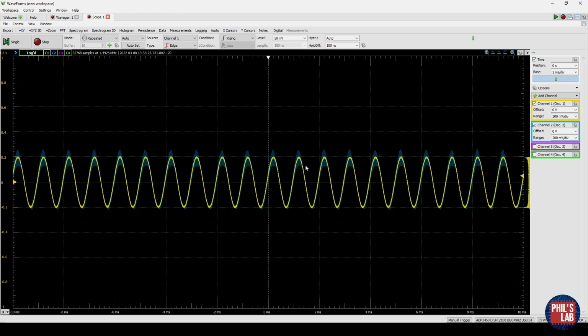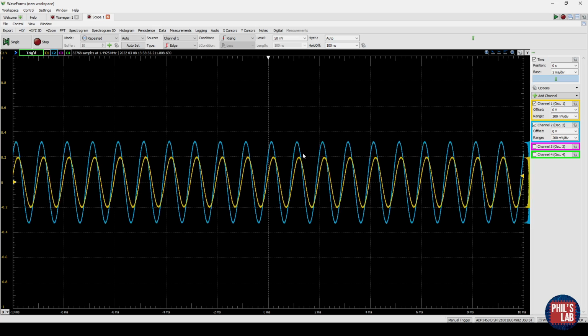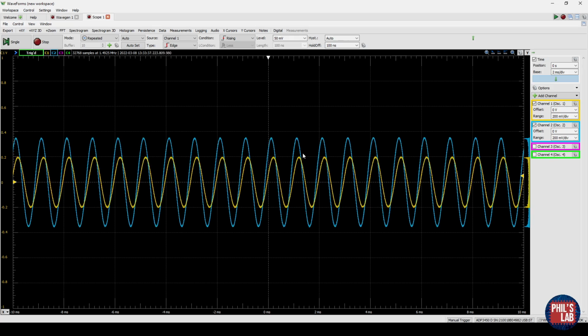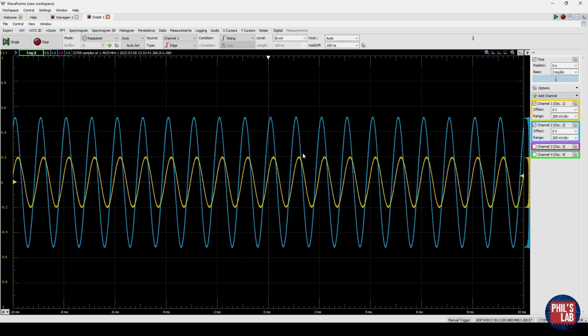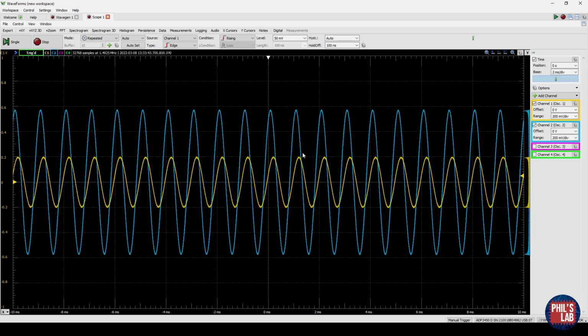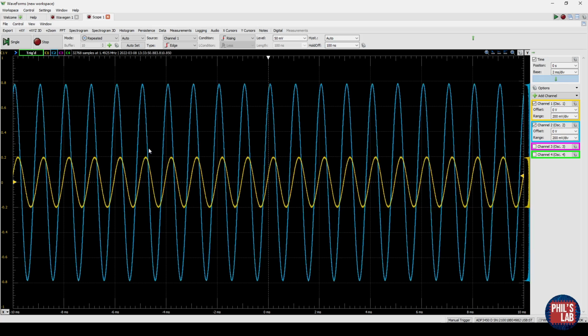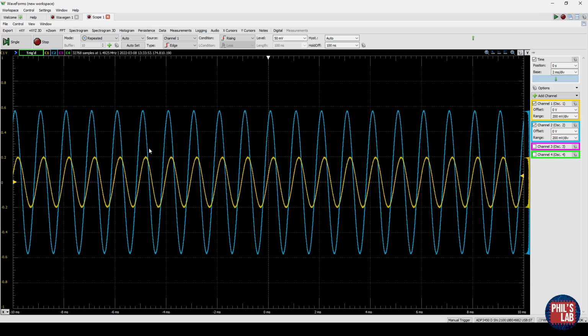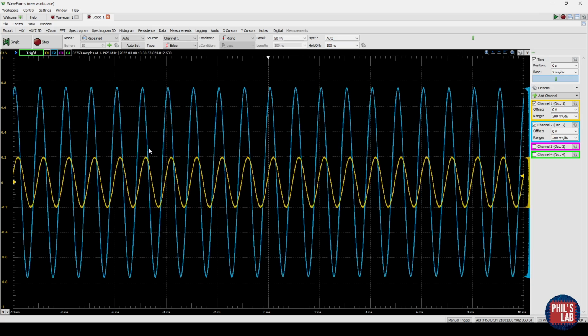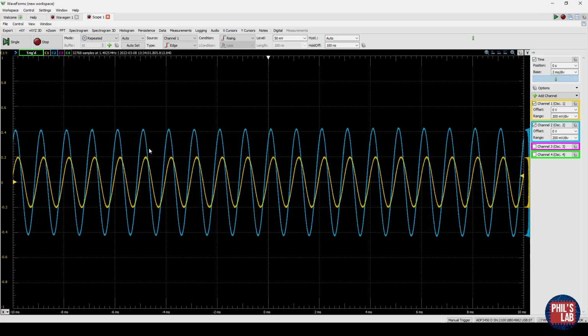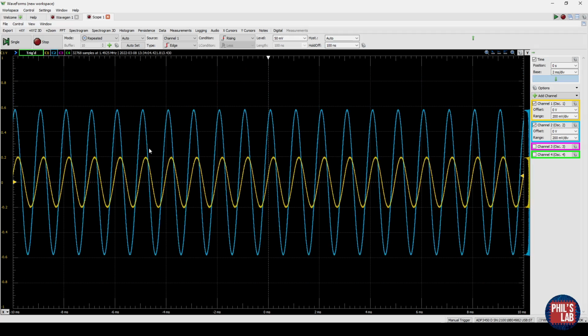This is because I've turned my potentiometer all the way down to make sure I have unity gain. So all of my output voltage is applied directly to the inverting terminal of my op-amp. If I change my potentiometer, so I decrease the amount of feedback, decreasing my feedback factor B, I'm increasing my gain, and you can see I get some sort of amplification due to the way I've arranged my circuitry. So it looks like by varying at least our feedback value, so we can change B, we can change the gain of the system as expected. So this looks like it's working.